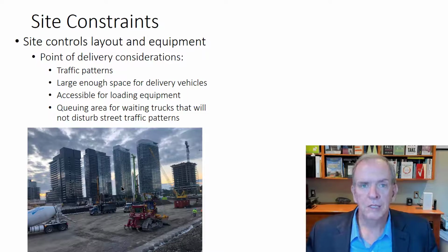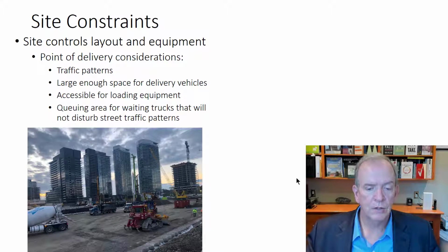Or you might have to consider, if you've got a lot of things going on at one time, that you'd have after-hour deliveries instead of deliveries during the daytime, or perhaps not during rush hour if it's a busy street where you're located. So you want to think about that in queuing areas, so where you can line up for your trucks. So you can almost see here, there's actually two dump trucks here, and there's an excavator over here. What you don't see in this photograph is over here on the street at the side, there's about 2 or 3 other dump trucks.